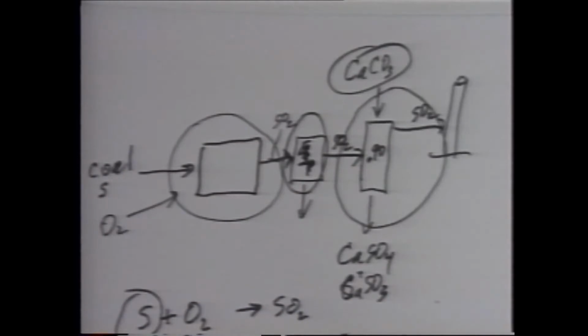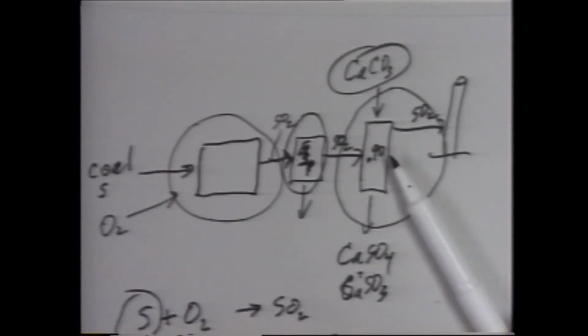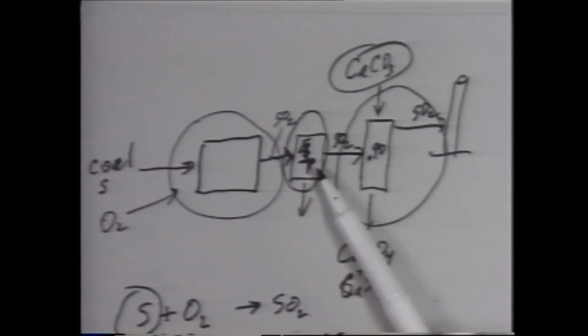It's going to be collecting that particulate matter. We're assuming no particulate matter collection occurs in the sulfur dioxide scrubber. That's conservative. You may get some particulate matter collected here, but you can't count on it, so you want to design the ESP to achieve the regulatory limit.